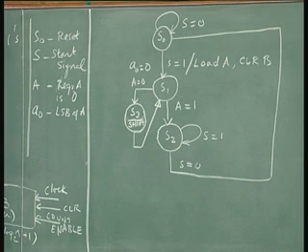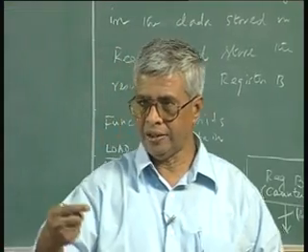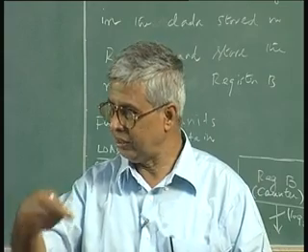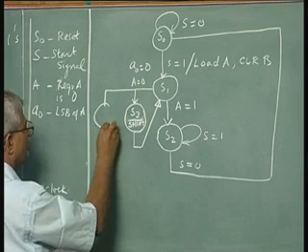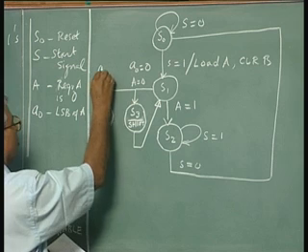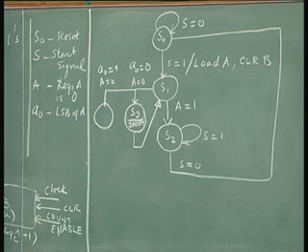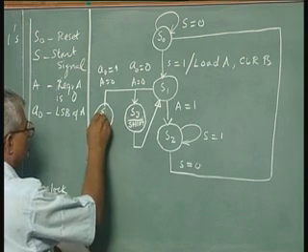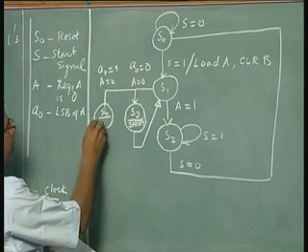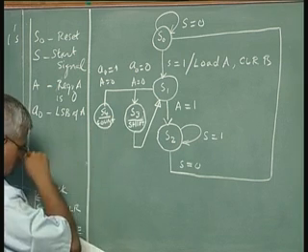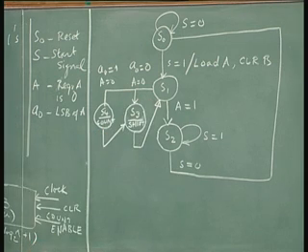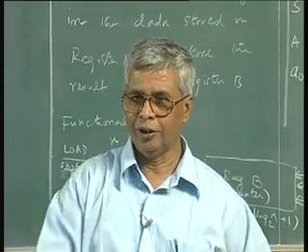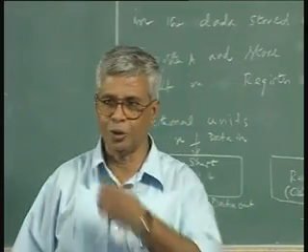On the other hand, if A is non-zero and A0 is 1, I should count 1, B has to be incremented by 1, then I shift and then I go back. So, A0 is 1, LSB is 1, I will go to another state called S4, and here I will say count. And then I go here and then I go here. I have not drawn it very neatly, I know, but I have developed it. You can redo it and make it look like what you see in books. That is not the point. The point is to know how to do it properly.